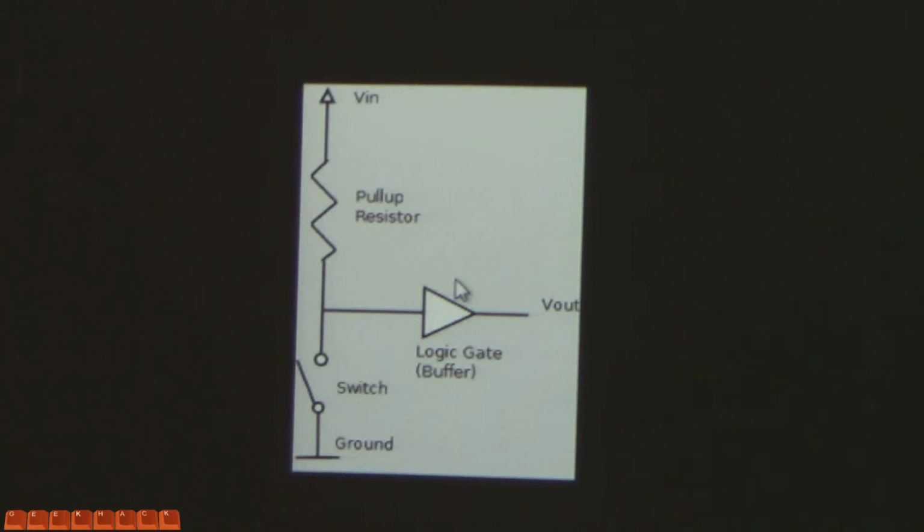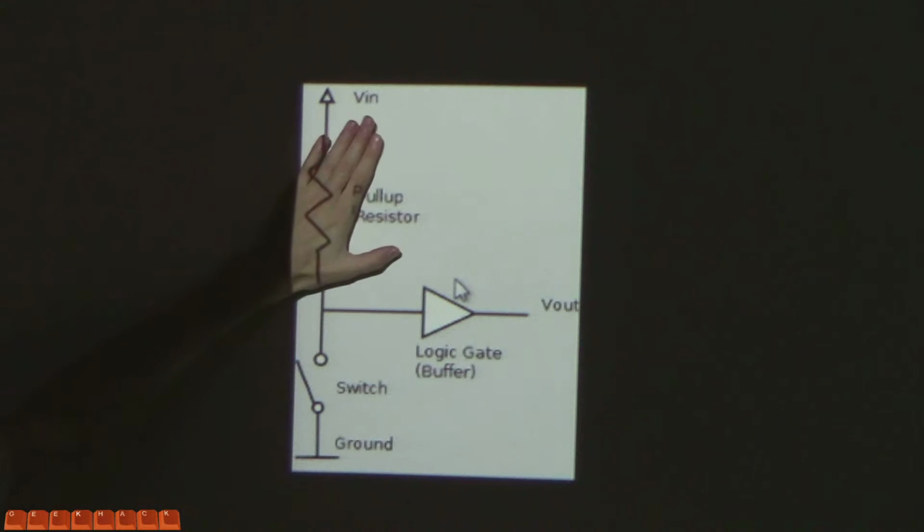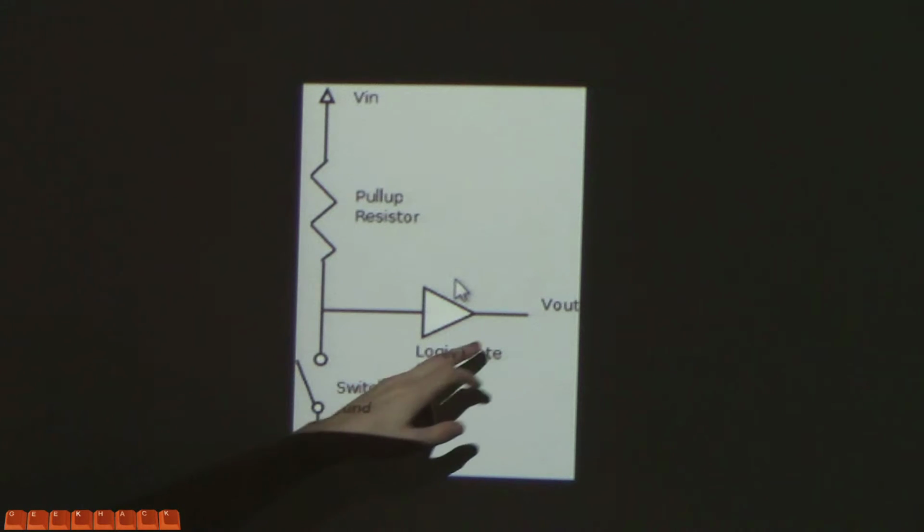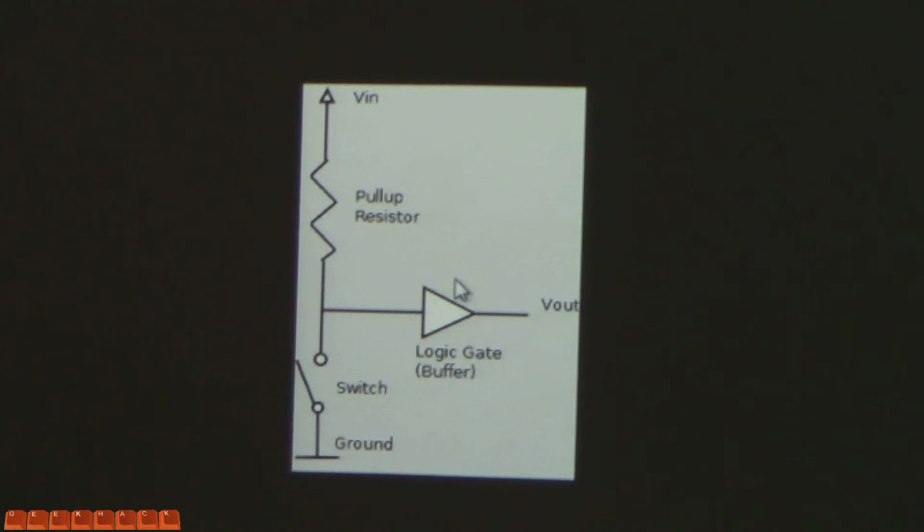You have to keep in mind that voltage is a relative thing. It's not a defined thing. That's why you need ground. That's why you don't need just one thing to power your light bulb or your phone or whatever. So when the switch isn't connected, what that's called is floating in electrical engineering. Floating means it's not doing anything. It could be 5 volts, it could be 2 volts, could be anything, because basically it's measuring itself. And the way that it's done, it just can't work. It doesn't work at all.